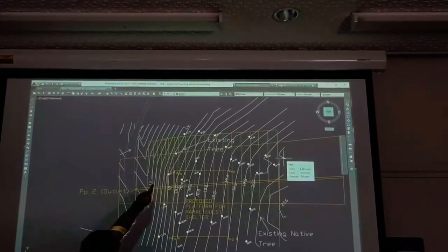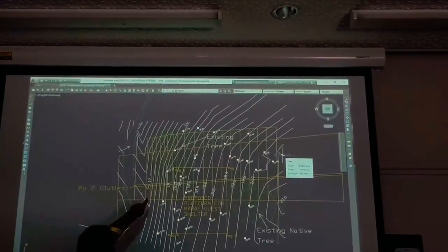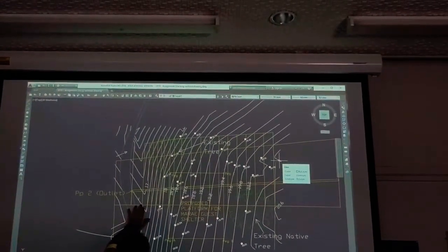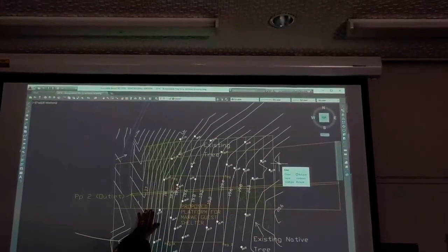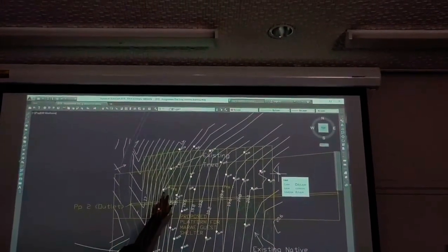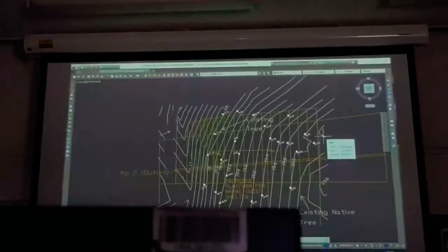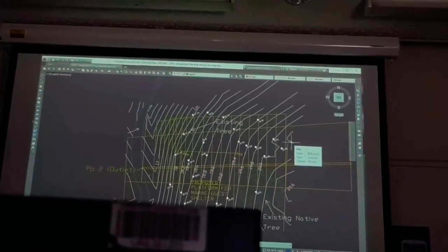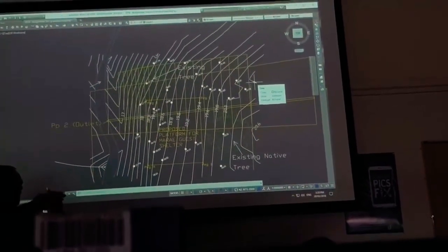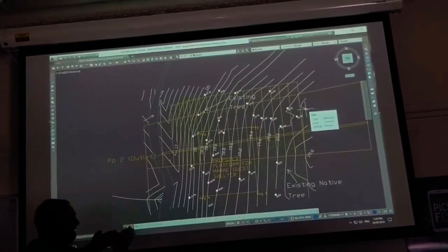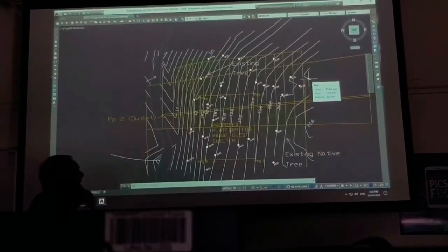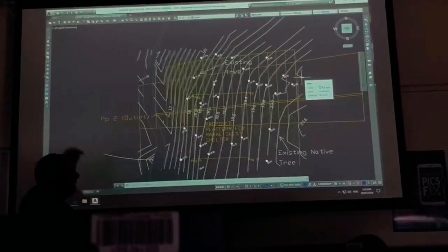And if you look up there, the trunk looks like it's going to be centred on about 17.6. It's going to be behind the platform and quite a bit high in the air. And I would say anything behind the platform, anything in the ground is going to have a dashed line. Anything above the ground is going to be prominent. So that one you'll see the full trunk, the full tree, but the bottom half will be dashed, the top half won't be.